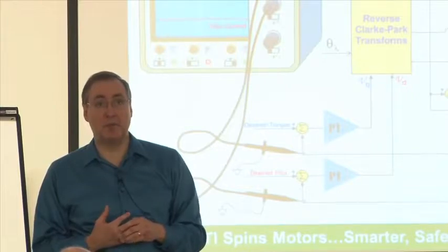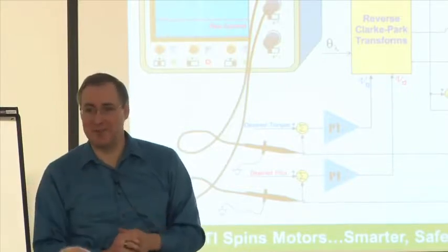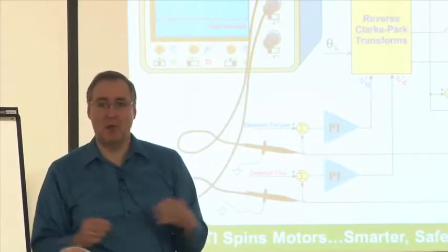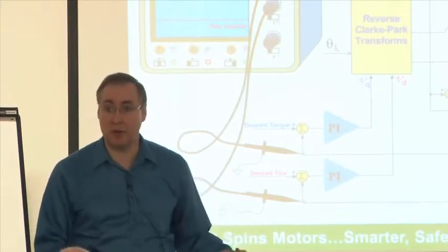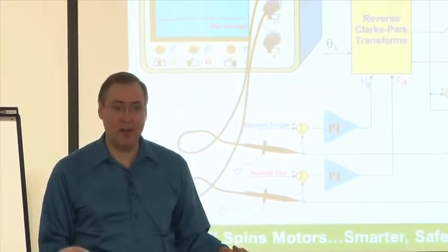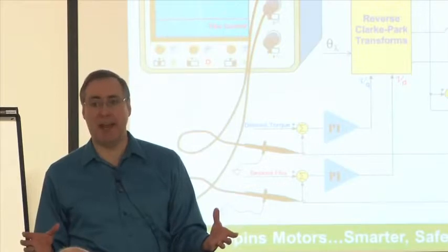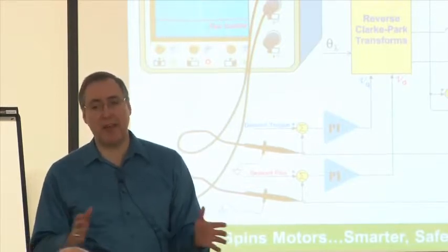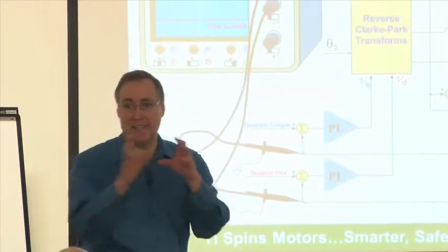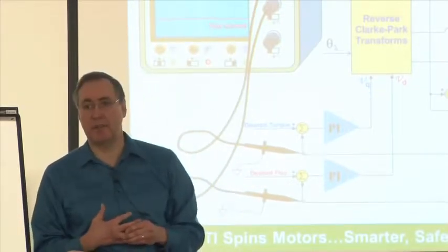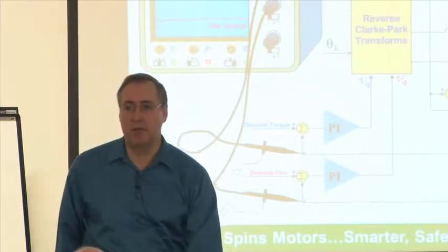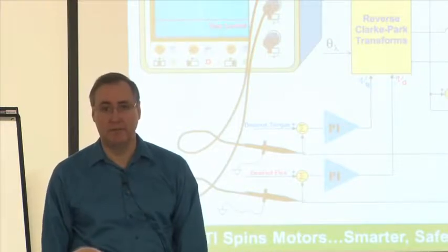And then the question becomes, I'll extrapolate on your question to ask the other question, and that is, well, what if you're sampling voltage waveforms and current waveforms? Well, again, all of them ideally would like to be captured at the same time, but at least that part of it is a little bit more forgiving. If you don't sample the voltages at exactly the same time that you sample the currents, it's a little bit easier to deal with, but you want to get those current samples as close to the same time as you possibly can to prevent motion artifacts. Okay? That is a great question.